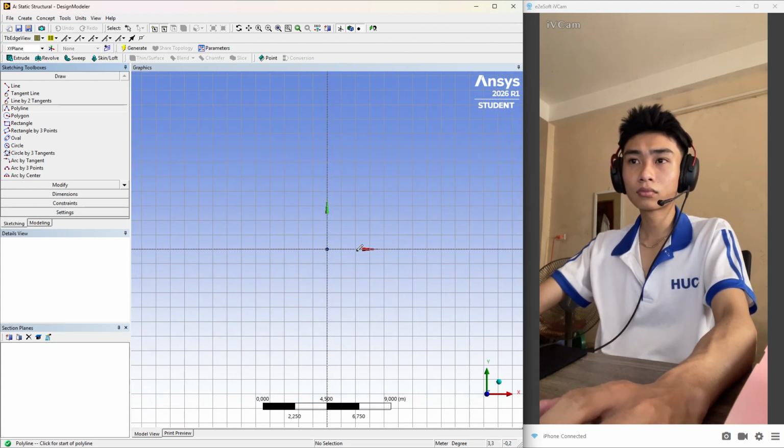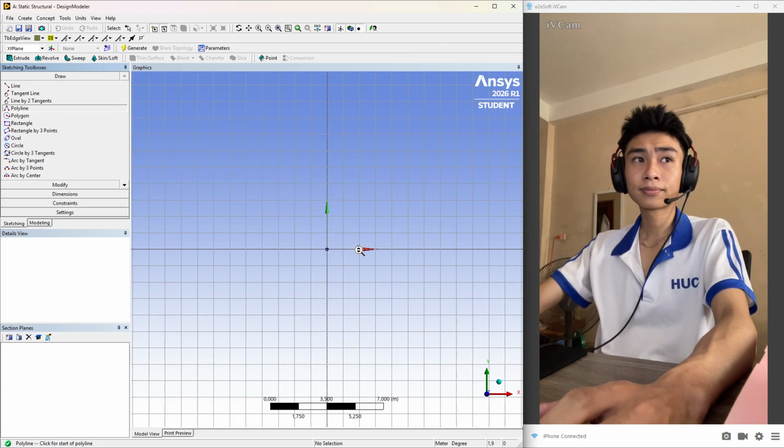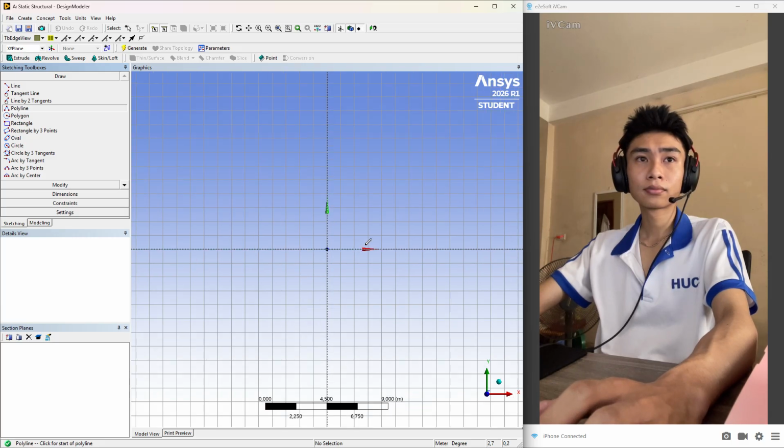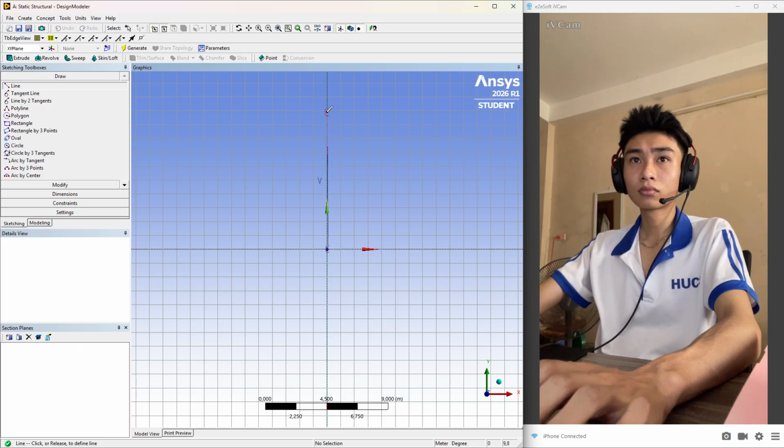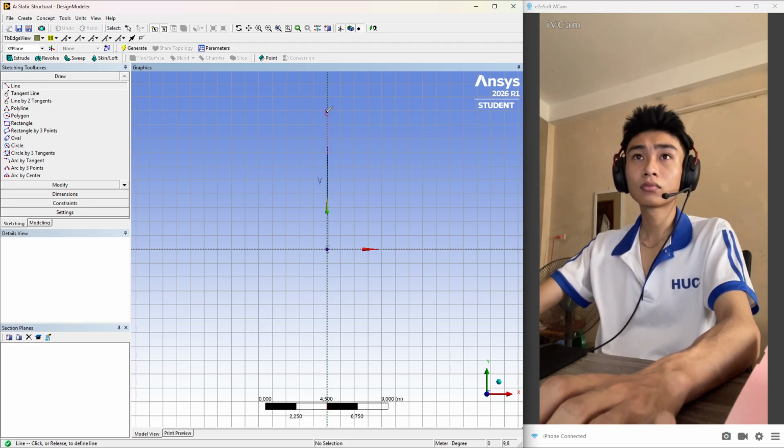See the point where point C arrives, click there and again go horizontally. Here no snapping occurs because we have not activated that option. We just have to focus on the horizontal and vertical lines. Once we have created all these things, right click and close end.